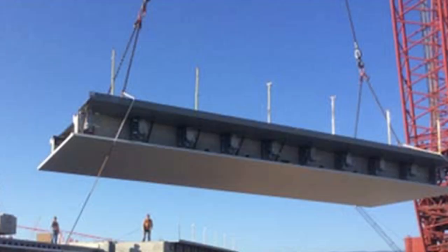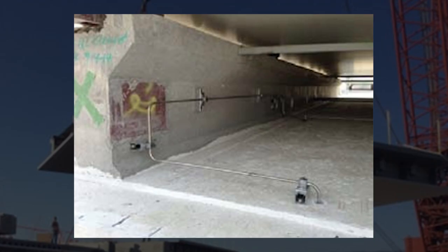In addition to mechanical coordination, the perimeter void slabs were highly coordinated with other trades. To facilitate construction and promote prefabrication, not only the embeds for the brackets were installed off-site, but also the brackets themselves. The plumbing for the mist sprinkler system was pre-installed in these units as well. And lastly, the perimeter metal edge deck form and temporary handrail were also pre-installed off-site. Prefabricating these activities off-site dramatically reduced on-site labor and equipment.